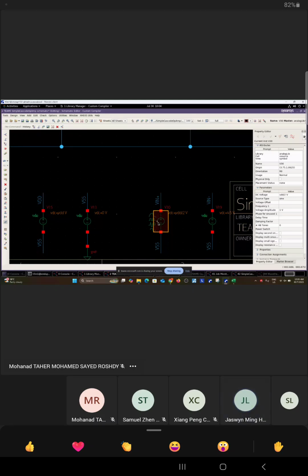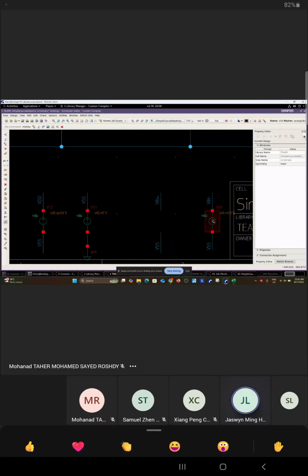You don't even need this because you are not doing negative feedback. In negative feedback, what we do in audio is we supply a sine wave to V in plus, and V in minus with feedback. So in this case, if you are doing open loop, actually you don't need this first. This one you need first. You replace back the VDC.